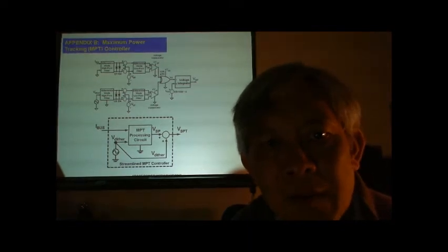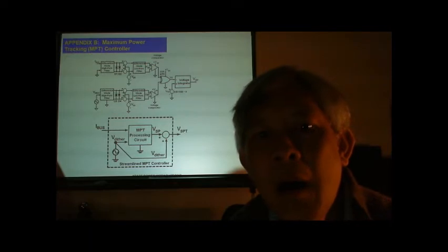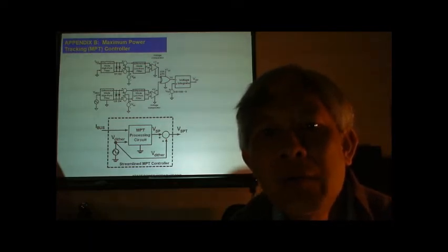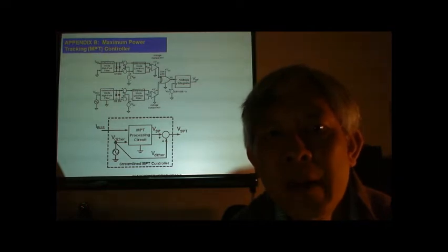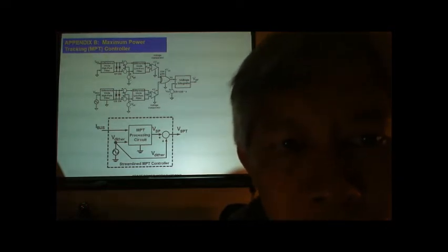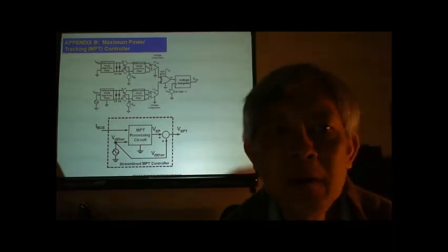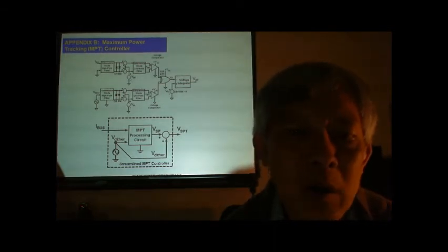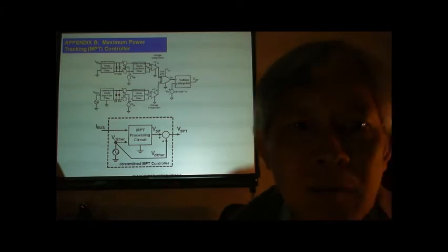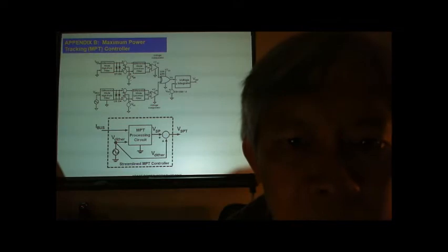They are processed together using a comparator to convert the analog into a discrete signal, and this discrete signal is processed by exclusive OR logic to generate the information with respect to the phase shift between the two signals, the power signal and the digital signal. The exclusive OR logic acts like a phase comparator.